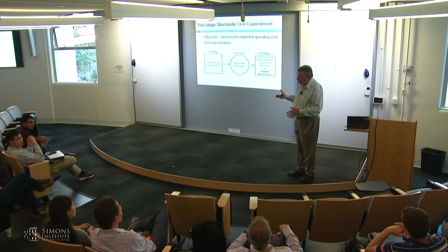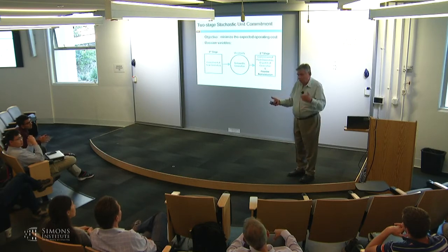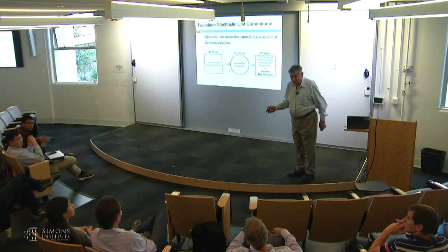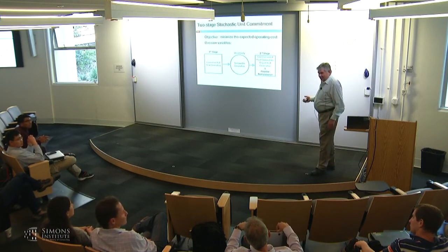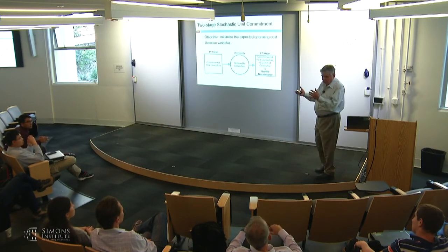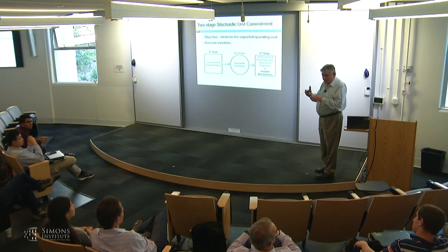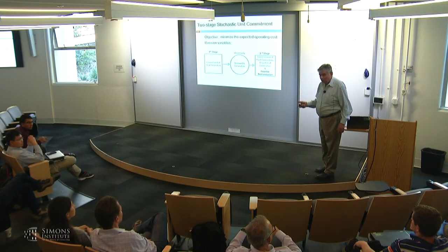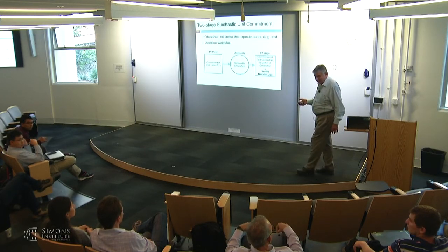Well, we actually have a theorem that shows that in a multi-period unit commitment, when you optimize over multiple time periods, even without congestion, you can benefit from changing the topology. And I won't go into that. We have a two-period example showing that if you have one period, no congestion, there is no benefit from disconnecting. But in a two-period optimization, you can have benefit from changing the topology even without congestion.